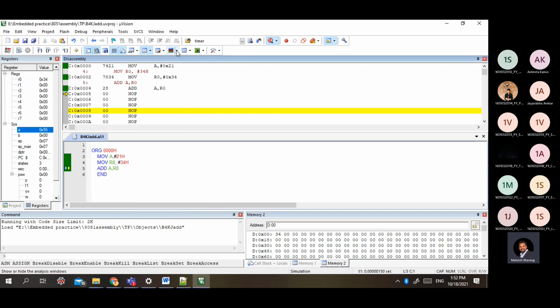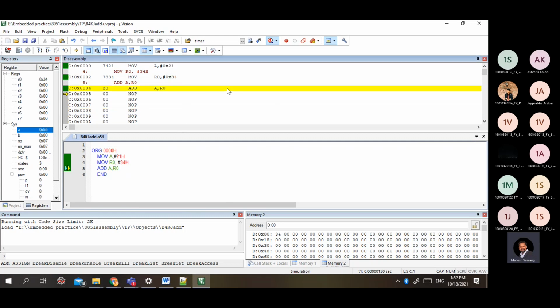Getting it? So if you want to check the signals on a pin, or if you want to see the graph of it, or how the signal is varying, that is also possible. You can go into the logic analyzer. You can enter that pin's name, and yes, you can get the waveform of that particular pin. Fine. So the rest of the tools I want you to explore.